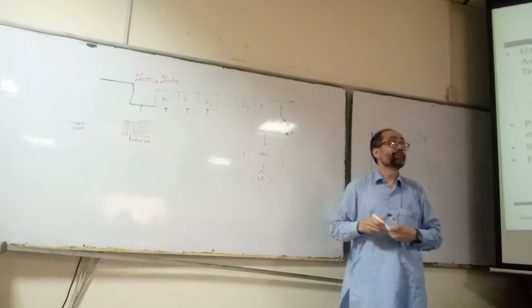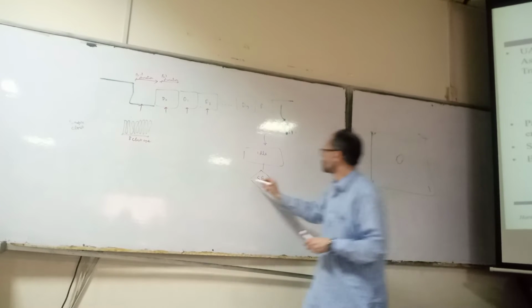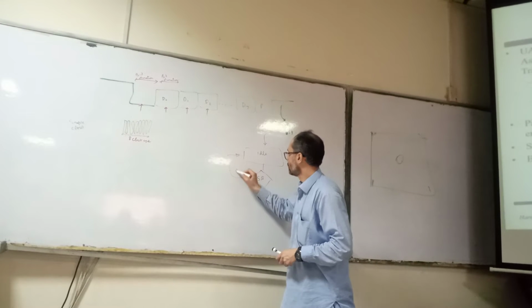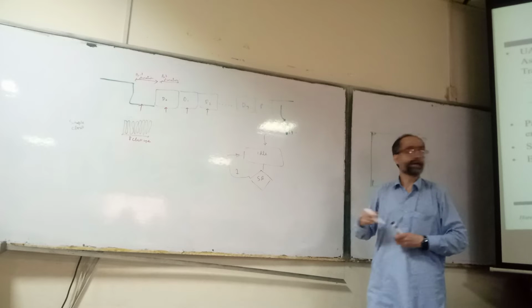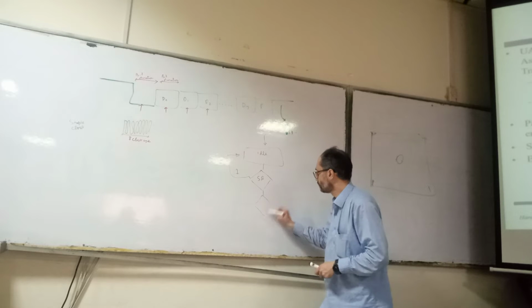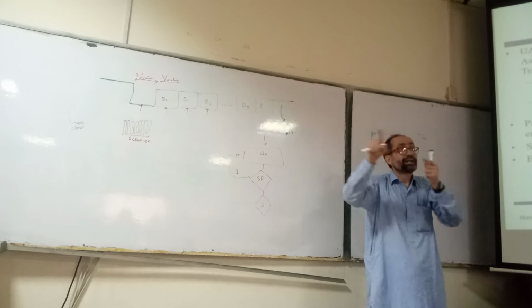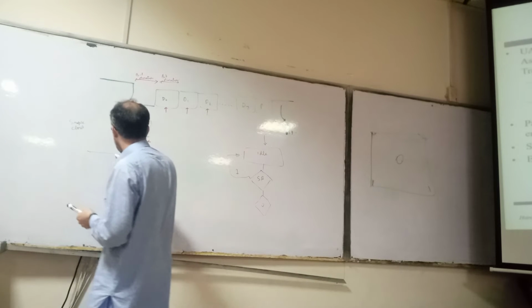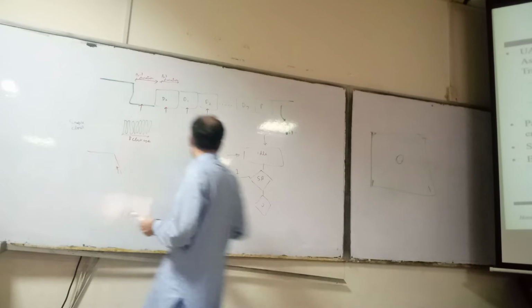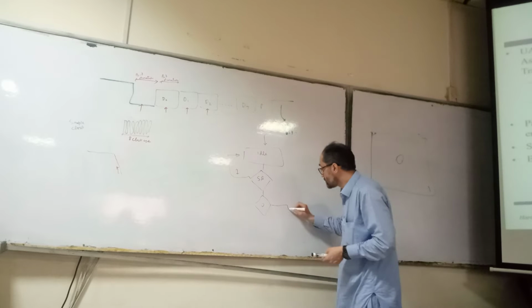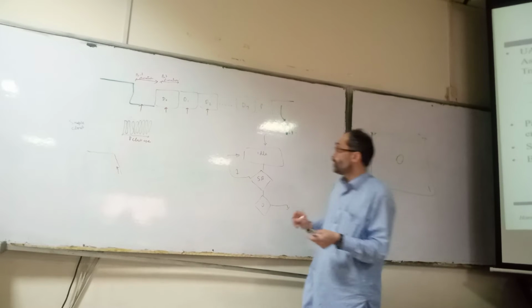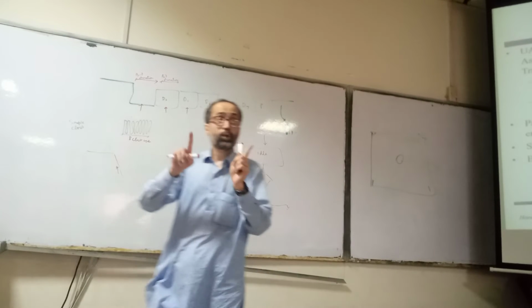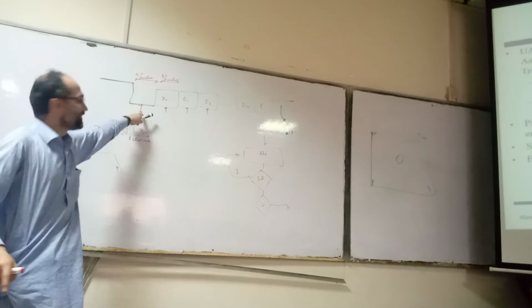If the bit is 1, what does it imply? No data, so it will stay in idle again. If it is 0, then we need the start. It means we are getting the start of the data. Let's assume it's here, so it means that now we are getting the start. It's 0, so then we need to reach the middle of this bit.